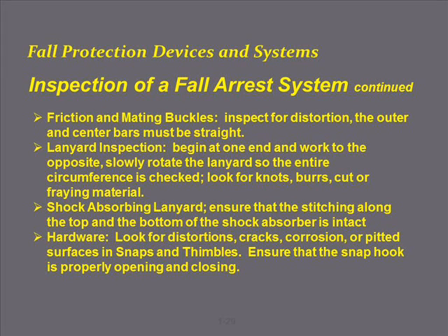On a lanyard inspection, begin at one end and work to the opposite. Slowly rotate the lanyard so the entire circumference is checked. Look for knots, burrs, cuts, or fraying material. For shock absorbing lanyards, ensure that the stitching along the top and the bottom of the shock absorber is intact. Otherwise, this would be a sign that the shock absorber has been used already. For the hardware, look for all distortions, cracks, corrosion, or pitted surfaces in the snaps and thimbles. Ensure that the snap hook is properly opening and closing all the way.